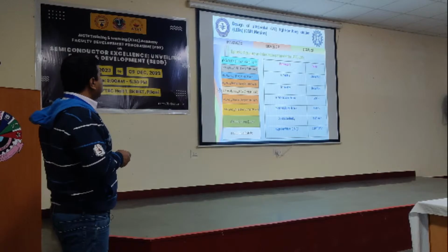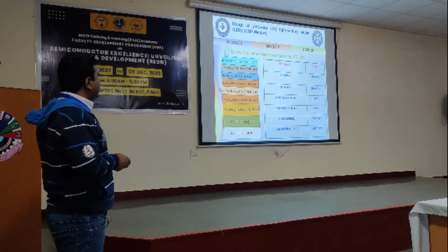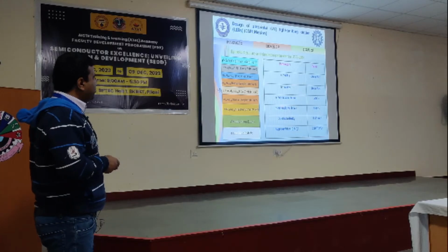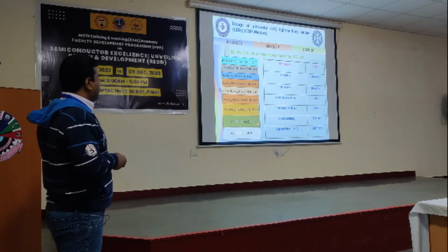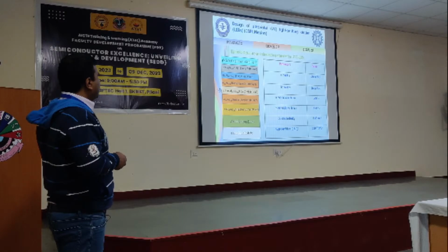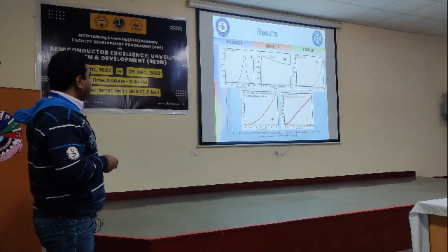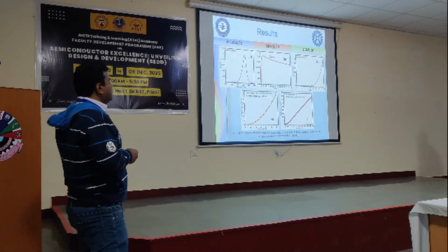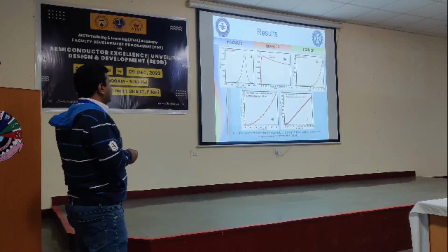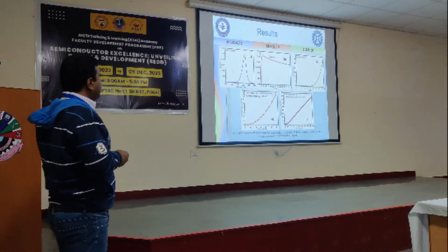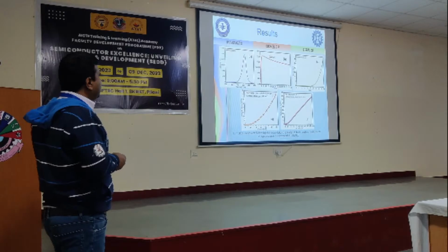You see, this is the simulation structure, and all the parameters you have taken, electron mobility, hole mobility, and the other simulation parameters as well. This is the structure of the material, okay, and this one is actually emitting UV light. You see the UVC region, that is actually 266 nanometer. In that case, if your peak is in this region, then the UVC region is achieved.